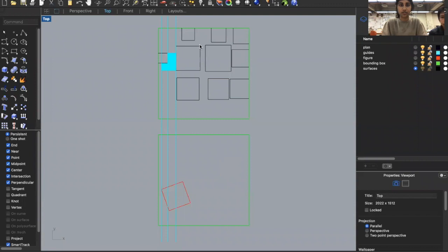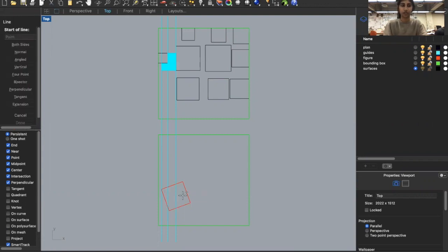So one thing to note is that all of your vertical distances in your plan are going to stay true, but all of your horizontal distances you're not sure, because this angle, when you look at it in plan, gets skewed. So for our vertical distances, if we drag them down and we draw them perpendicular to our figure, we're going to be able to get the outline of our shape in its true dimensions.